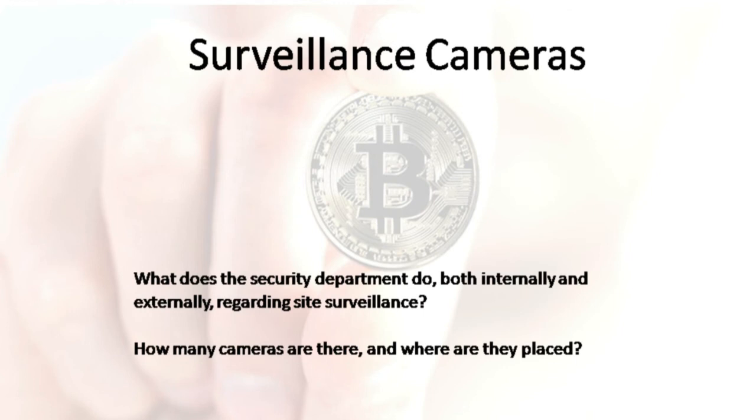Deploying surveillance cameras inside and outside of the facility is a must, as it not only records the events that are happening, it also deters theft and vandalism to a certain degree. Security cameras should be installed at locations that maximize visibility and should have redundancy so that if one camera is down, there should be another one at a different angle that can see what happened.